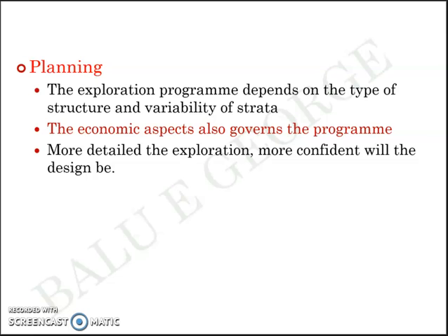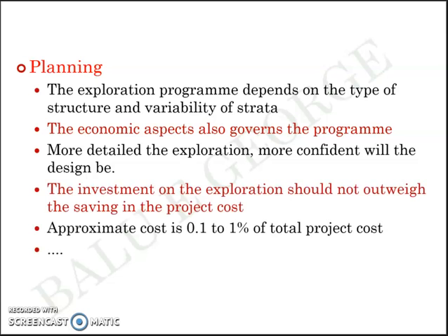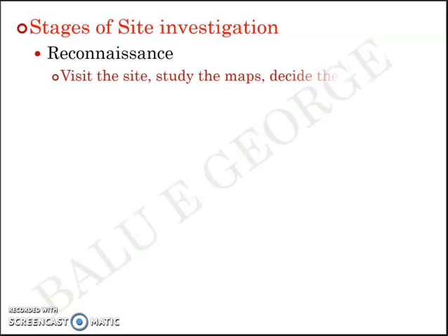And the investment on the exploration should not outweigh the saving in the project cost. The approximate cost is about 0.1 to 1% of the total project cost. Now, the stages of site investigation include, number 1, reconnaissance, which means you visit the site, you study the maps and decide the programs.